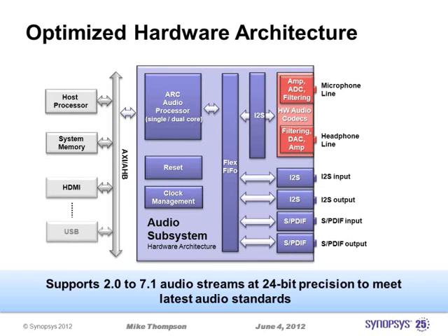We actually partition the analog codecs themselves off chip, or outside of the subsystem, because we don't know what process you're going to run those on, whether it's 65 or 40 or 28 or an older process for that matter. But I'll show you a slide in a minute. We verified all the way to the interface so you can easily attach any analog D to A or A to D that you want to.